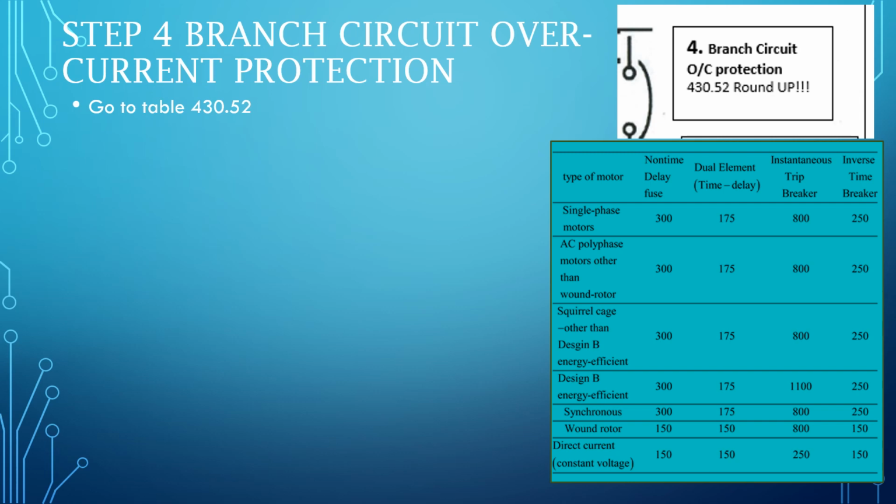Now, depending on the situation that you're in, you may have a different one. If I have a motor that's drawing 18 or 20 amps, and I am putting that on a 60 amp breaker, that spike of inrush current at 60 amps is not going to trip that breaker.